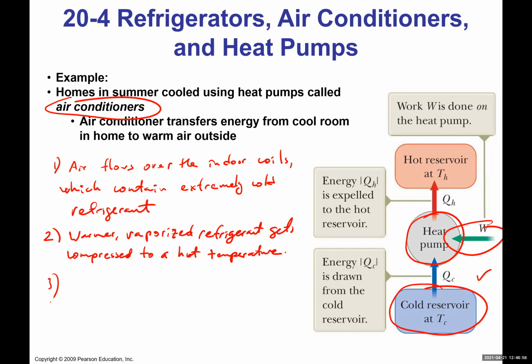Okay. Now let's look at step 3. That means we are releasing heat to outside. Remember, that was one of the important points, right? So basically releasing heat to outside. Now step 3 will be, once we have the refrigerant, it's still relatively warm. I mean, we were talking about 120 degrees Fahrenheit for the vaporized gas refrigerant compared to the outside.